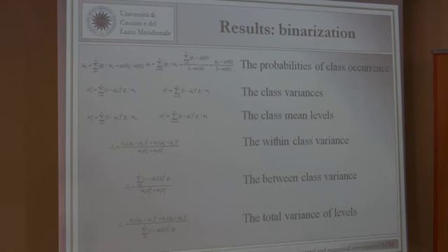We proceed in this way. Make a metallographic photo on the surface, then we grind the surface about 3 microns. We prepare another surface, metallographic preparation, and take another photo, and so on. In this case, we have the presence of different layers of material, and we can rebuild the 3D model in this local position.